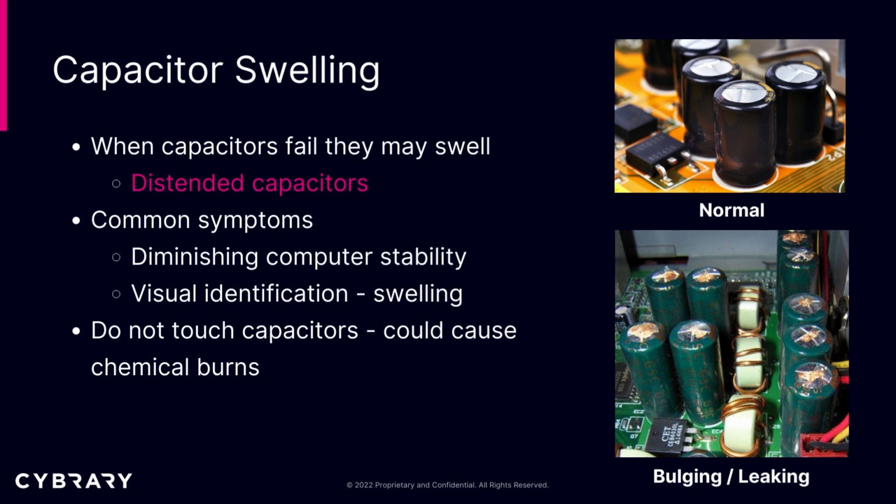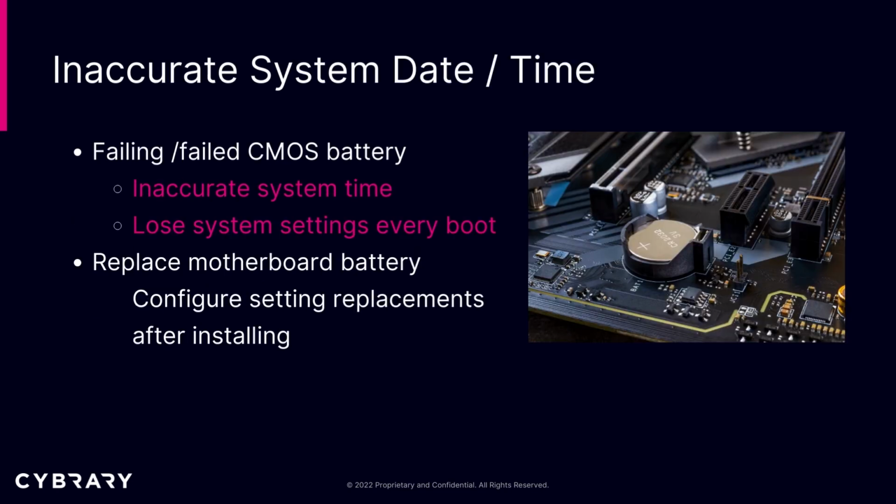Now, when you come to a situation like this and your capacitors are swelling, these capacitors could be replaced individually, or depending on the capacitor, you may have to replace the entire motherboard. Again, check with the manufacturer for their recommendations here.